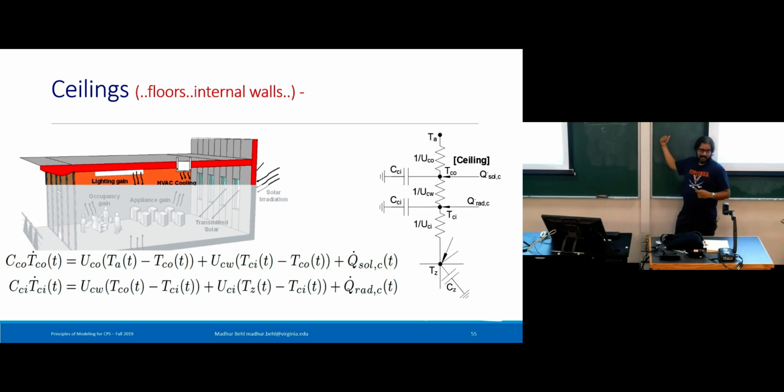But this wall behind me is connected to another lecture hall, which is thermally conditioned. So maybe the temperature there is different from the corridor temperature. So if I had to model this very room, I may just aggregate all of these walls into one 3R2C branch and drive them with the corridor temperature. I may model this one separately because of the temperature adjacent to me. Same goes for the right-hand wall. Same goes for the ceiling and the floor.